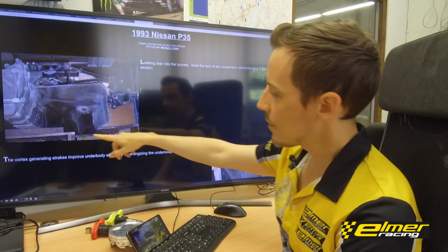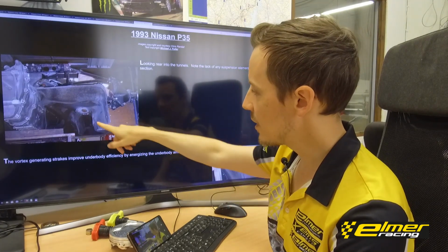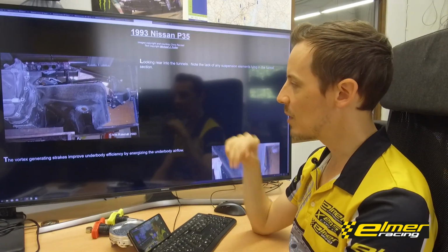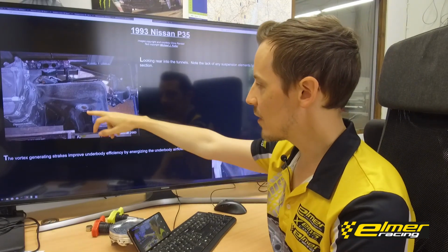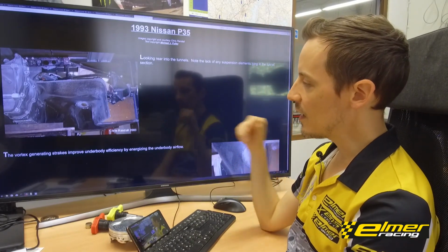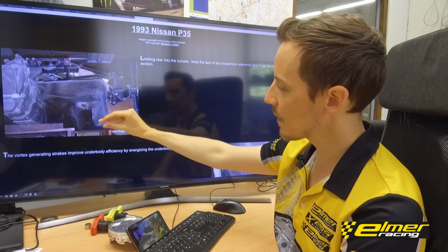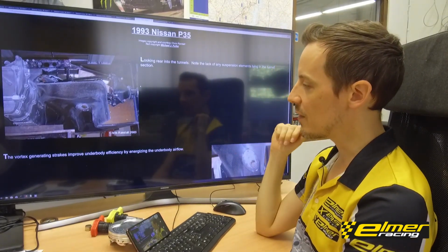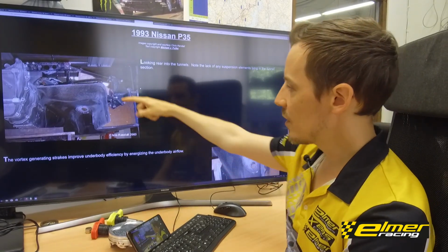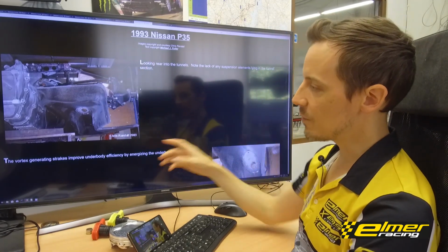And here's another angle on how these tunnels look. They were using blown diffusers way back in '93 already, probably maybe even before then. You have the exhaust blowing in here, and that also aids in the air velocity underneath here, which of course increases the air velocity in the narrow section there that is actually producing the downforce. Some interesting stuff. And here of course you can clearly see that all the suspension components are outside of that tunnel, so that greatly reduces the turbulence there.